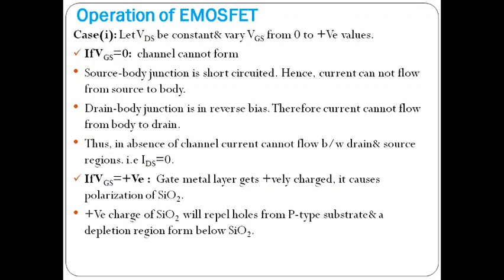It is called threshold voltage. Clear? So now we created the channel by applying the positive gate voltage. Now we discuss the operation of enhancement MOSFET. In this, we know VDS is used to drift the carriers from the source to drain, and VGS is used